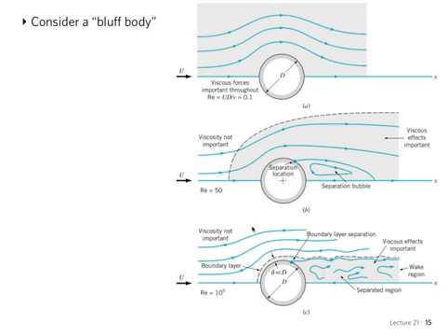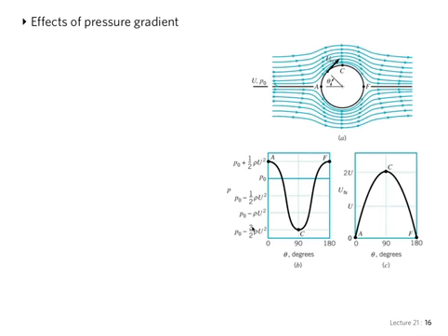So let's discuss this idea a little bit more. So this is related to the effects of a pressure gradient. And so as with the case of the flat plate, as I was saying, boundary layers are normally thin, okay? But the pressure gradient is not zero for a curved object. In the flat plate, if you recall our discussion of the boundary layer, we came to the conclusion that the pressure gradient was zero. The pressure actually was constant throughout.